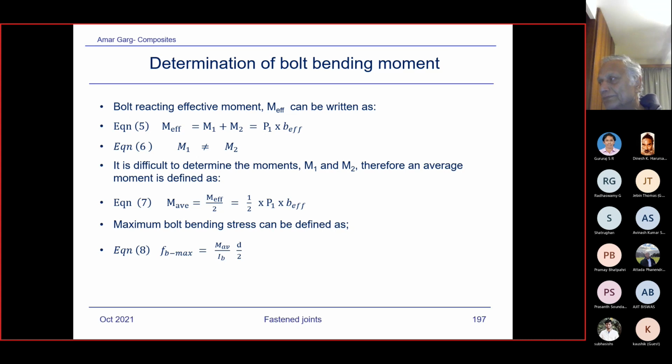Sir, so basically the pull-out strength automatically increases, right? Well, this can pull out from the head side, not from the washer side, but okay, only in the case when the washer is there. But suppose you have blind fasteners. A rib to skin on one side will be attached by a blind fastener, like a composite lock, say.